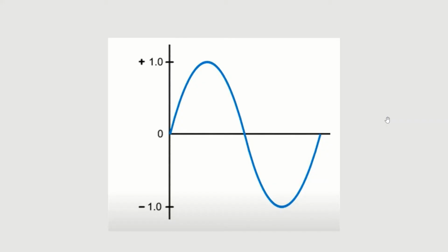This alternating of electric flow generates a wave flow as the electricity alternates direction. This is called a cycle. In other words, one rotation of the wire in the magnetic field. The time it takes one cycle to complete is called a period. How many periods happen in a second is called hertz.